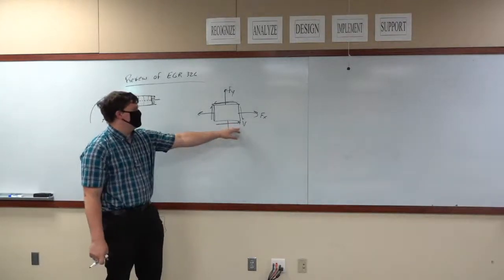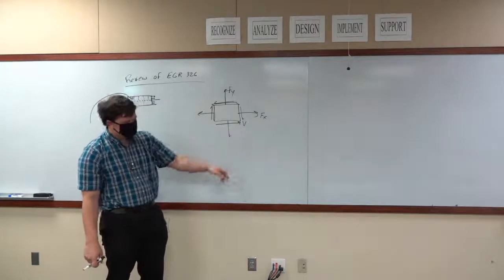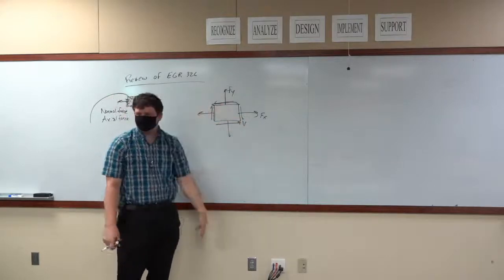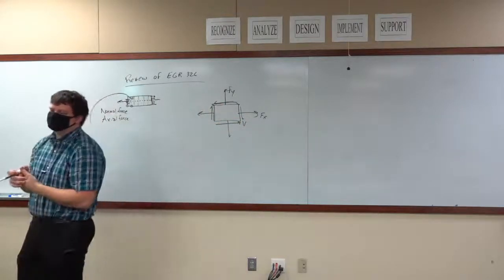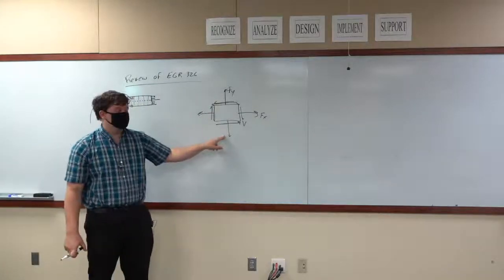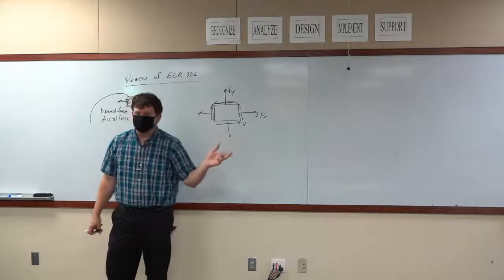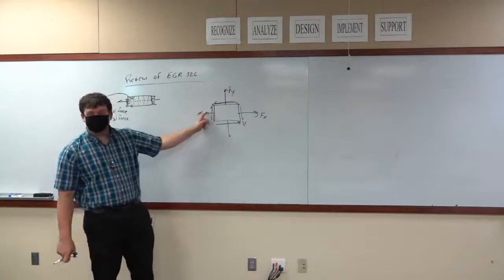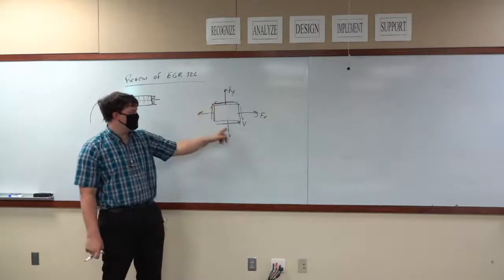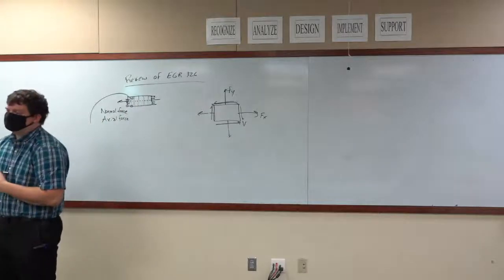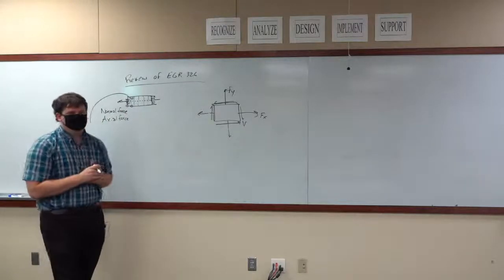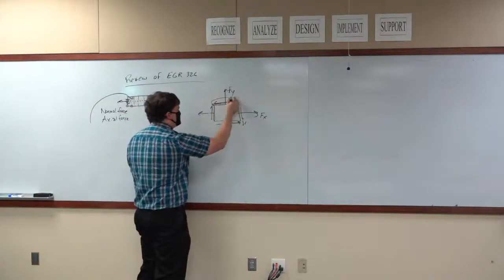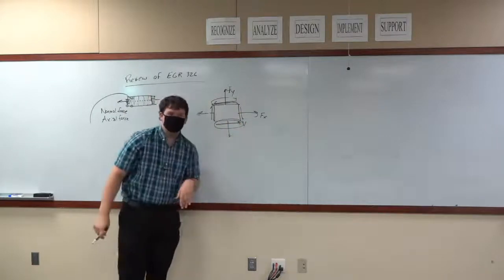So why is it that the shear force is 4 forces? These forces have opposites, right? That's the equal and opposite reaction. But why is it when I exert shear force V downward, I don't just have one on the other side that's opposite? Why do these other two show up? Because otherwise it would cause it to rotate. Okay? This force and this force create an opposing moment.